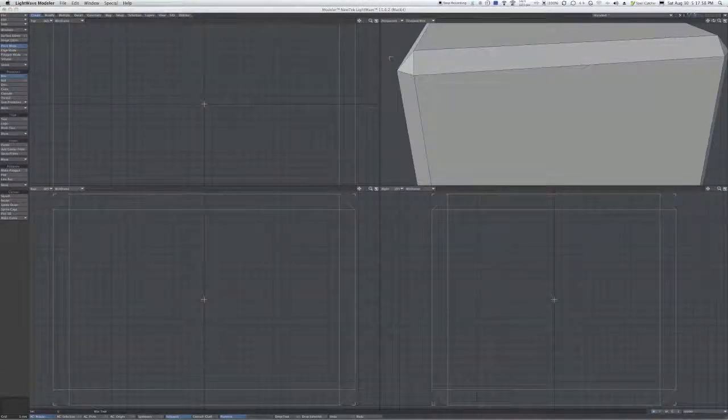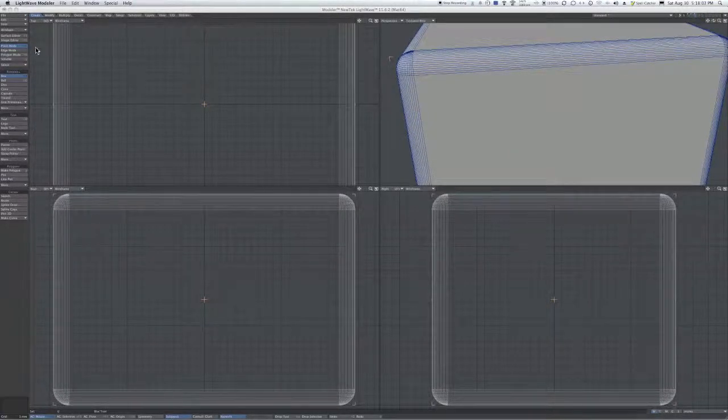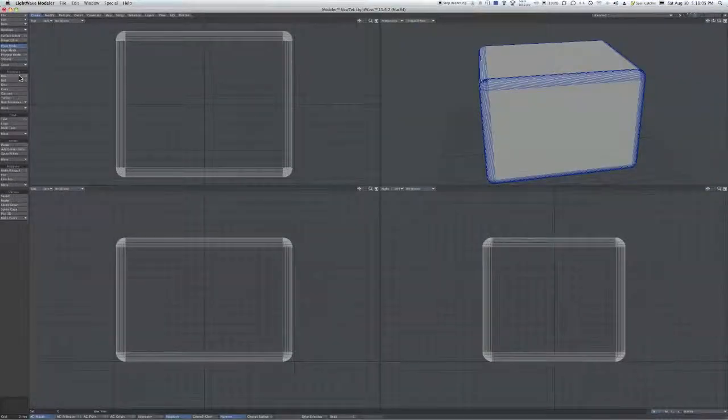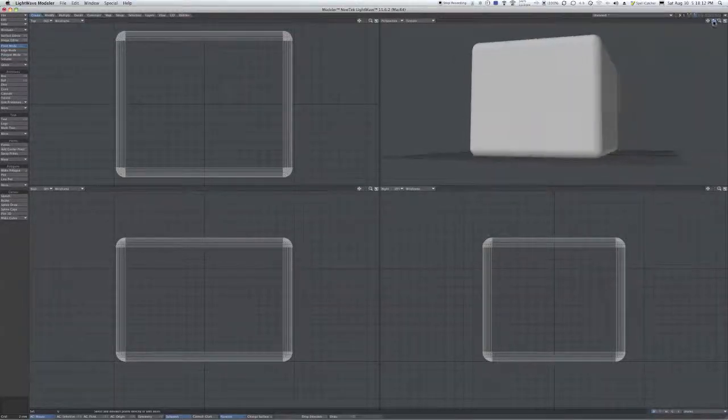Numeric. Now this time I'm going to give this a bunch of segments there to be rounded off. Okay, and so when you're looking at this, that's a nice rounded box. But the chances are that this bottom edge is just going to look bad. So if you want rounded edges, I would say stick with them on the sides and the top. They'll print fine there. But the bottom, wherever it's rounded like this, is going to have a problem.